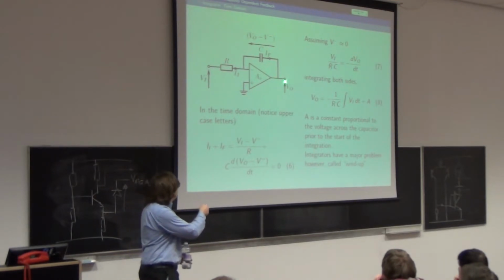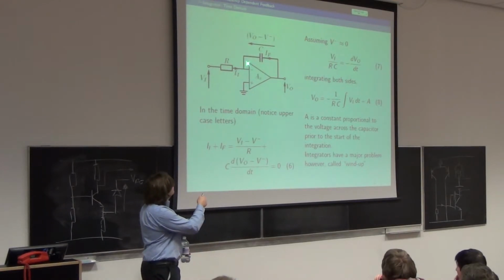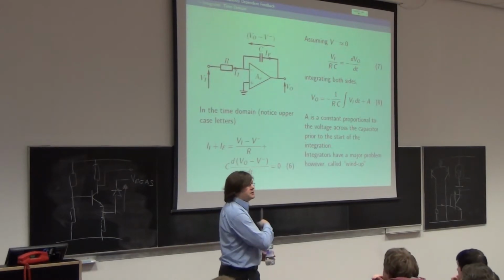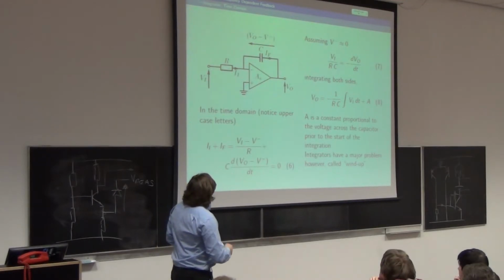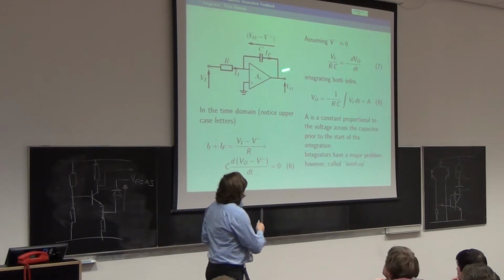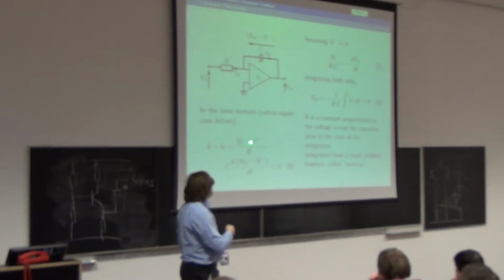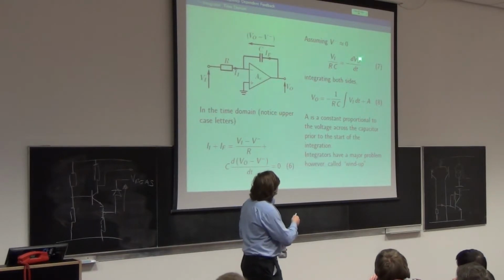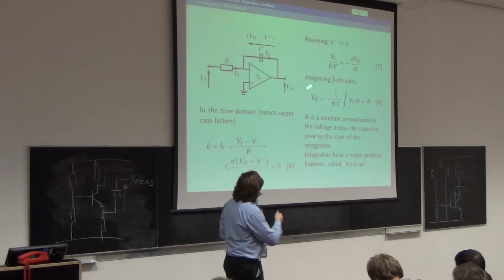That's V minus and that's V out. And then you set it all equal to 0, because you can't have any current created or destroyed on that node. So this is the same analysis as 118, it's just now that there's a capacitance instead of a resistance in the feedback. So assuming V minus is approximately 0, so A_OL infinite, that drops down to this, because V minus becomes 0, essentially. And then if you were to integrate both sides to get V out, so you take away the differentiation and take the minus sign across, that drops out.